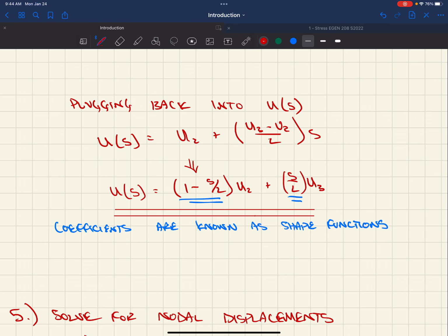This is the most simplified version of the finite element method right here, okay? Just want to make sure you know this, because this is what Visual Analysis is doing, ANSYS is doing, ETABS, RAM, RISA, all of them are doing this. Based on selecting an element that has a displacement function, an assumed displacement based on nodal values. Okay. This is what we would call our interpolation function.